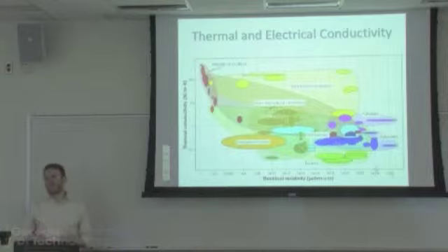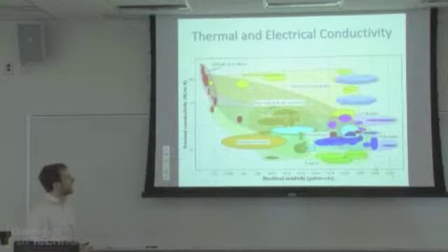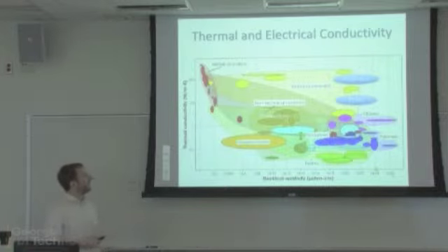So when you're talking about manipulating the thermal properties of a material, a factor of 10 is actually a significant change, whereas you might not think anything of just changing the electrical conductivity of the material a factor of 10. So as I talked about some recent work, people have taken polyethylene nanofibers up here to metal-like thermal conductivity, and then polyethylene films up to another high thermal conductivity, but these are obviously highly electrically resistive.